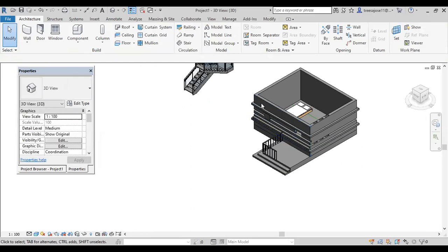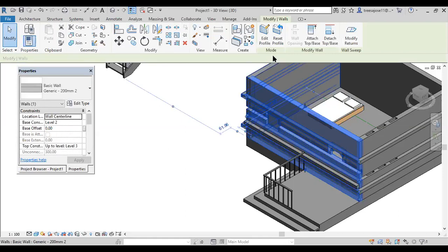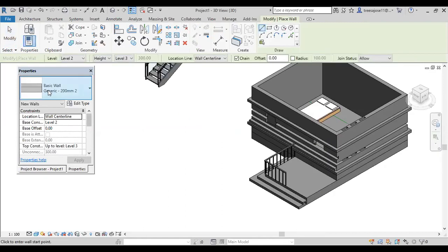There is one more option, a new option. For example, I have to create a wall with this similar property, wall or window, whatever it may be. We don't know what the name of that particular wall is. Otherwise, for example, in the case of furniture, you have to place those furnitures with different parameters. Then you select this one. There is an option called create similar. Then automatically the system will select the wall name.